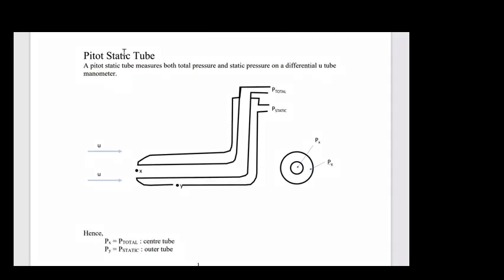So what does the pitot tube actually do? Well, it measures the dynamic pressure. Here we've got the same scenario: our fluid flowing from left to right, with only a horizontal component and 0 vertical component. So position X here is exposed to atmospheric pressure, it's outside. It's also exposed to dynamic pressure due to the fact that this fluid is moving at a certain velocity. So X is measuring static pressure and dynamic pressure. That gives us our total pressure.